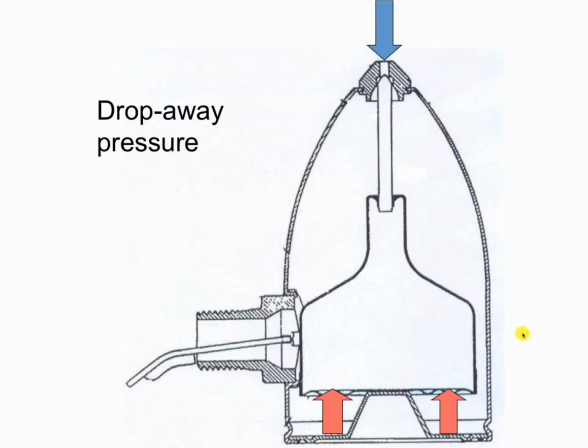Now, I do want to talk about what he is mentioning here, as far as the vent being able to open back up again. What you have, let's just call it a thermostatic element, inside of the air vent, just to simplify it. As he mentioned, it's filled partially with water and alcohol, and when the steam hits it, it brings it to a boil, causing the bottom of this to push up on this bottom piece of the air vent.